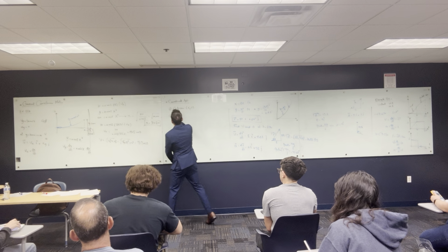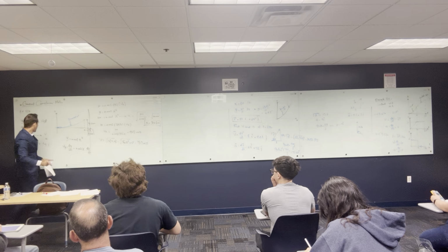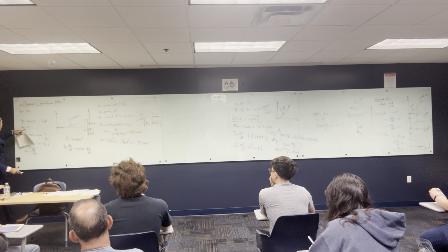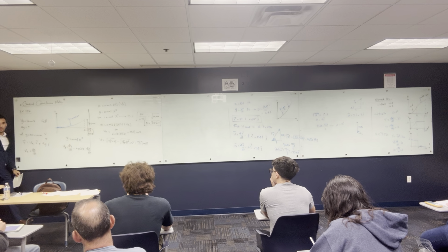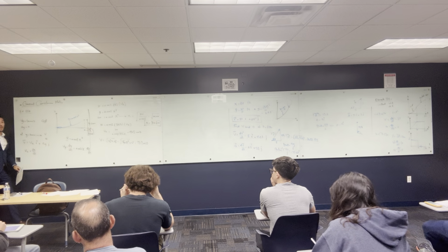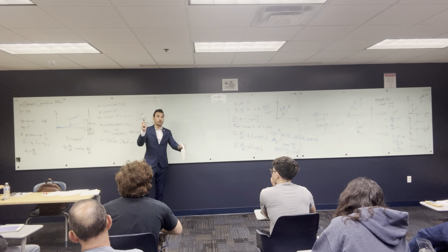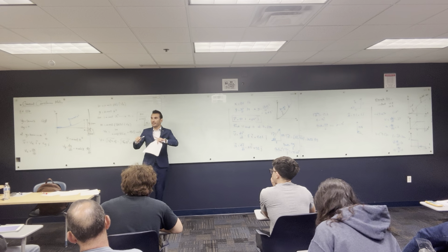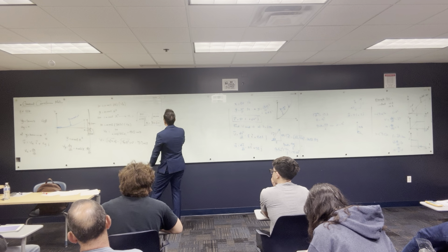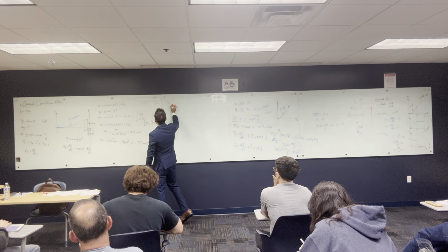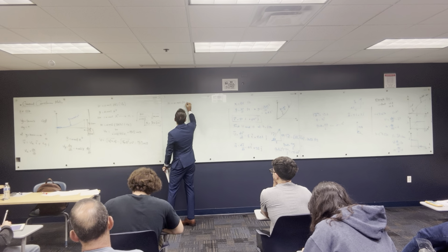Let's get the acceleration. To get the acceleration, you have to differentiate something. By the way, I know here that velocity Vy is constant, so we were able to find out that Ay is equal to 0. So Ay is a done deal. Let's find Ax. To find Ax, you need to find an equation that has Vx and differentiate this equation so that you can generate Ax out of the Vx. This is the only equation that I have that has Vx, so you are going to have 10 equal to 0.002 x Vx.